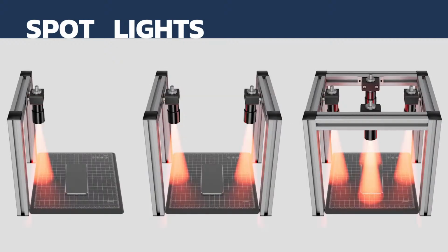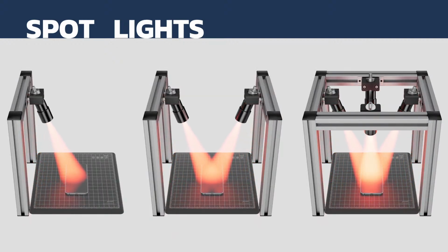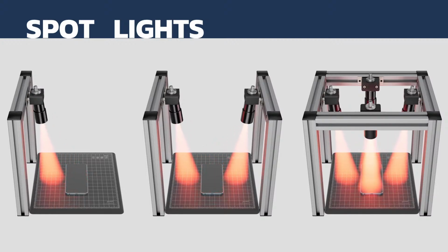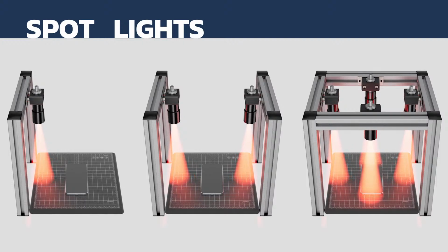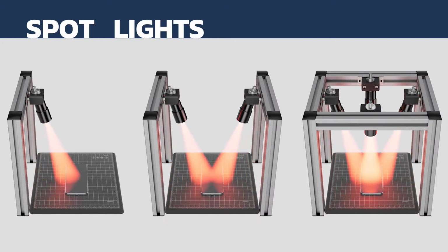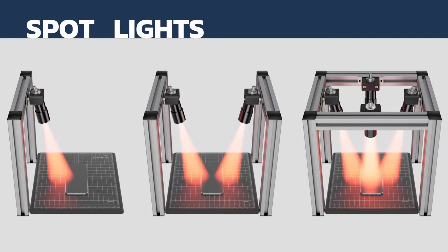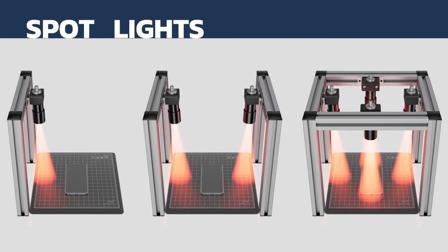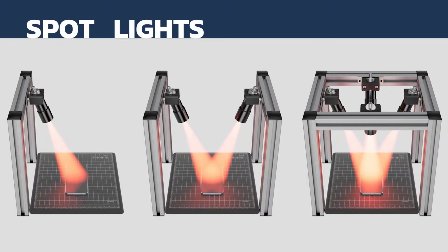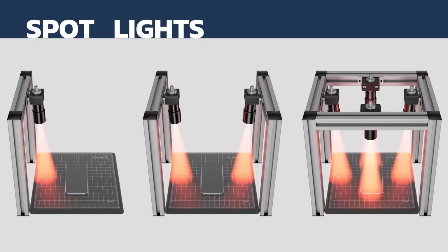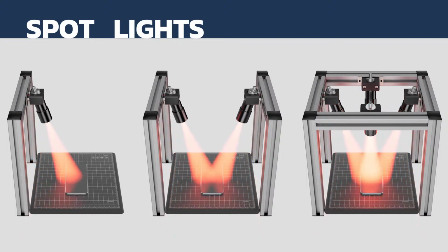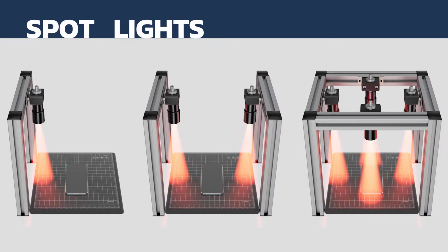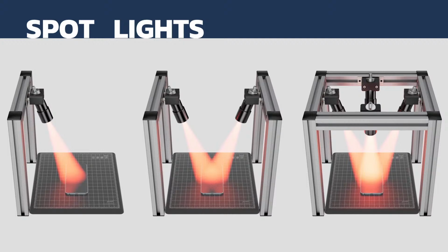You heard me allude to that a single spotlight can be limiting, cause shadows and other things. In simple applications, maybe we only need one light source again. But in cases where you're getting uneven lighting gradients, having problems with shadows, or just need to get light around an area but you have limited points of access, you can see in the middle and right-hand diagrams that we've added cases to use 2 or 4 spotlights and join the spots together in the middle to illuminate bigger areas from multiple points. Spotlights are really good for this. And a spotlight, again, is a low-cost form factor.